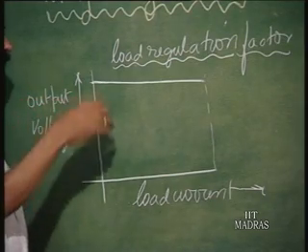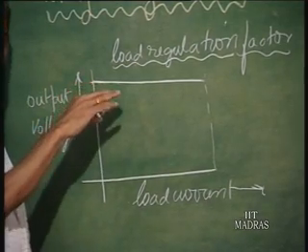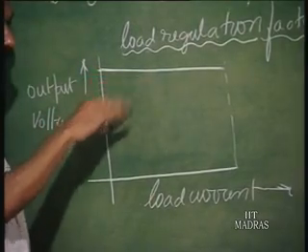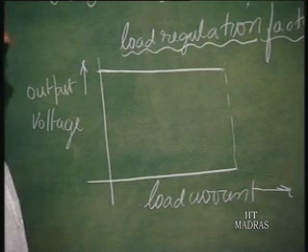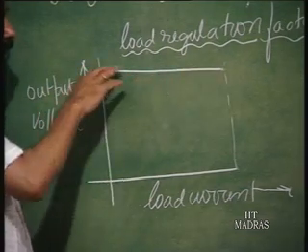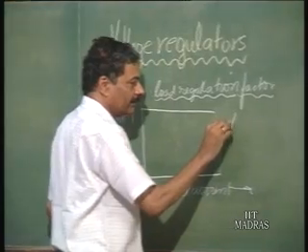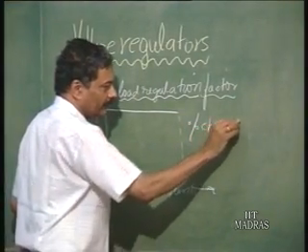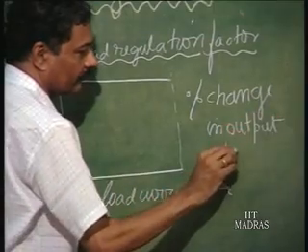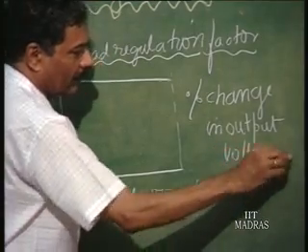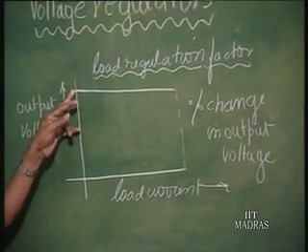Right. So, that may not be linear for large change in current. So, I cannot represent it as a physical resistance, but there is a small drop as you increase the load current enormously. So, this is called load regulation. What is it? It tells us the percentage change in output voltage that will be from no load to full load.